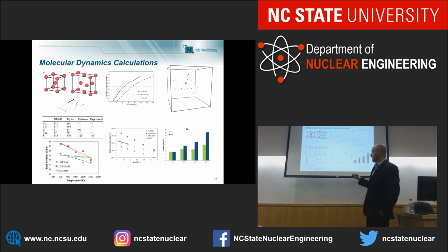So, what's also interesting is that we're looking at it for the 3 different interatomic potentials that we utilized up here as well, and we get a variety of softening behaviors. There's a lot of scatter, even though these are decent interatomic potentials that get a lot of information right. This is all very large changes in the amount of softening and in what the bulk modulus actually is. So there's a lot of uncertainties involved here.